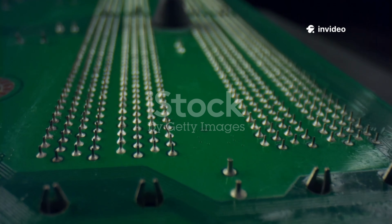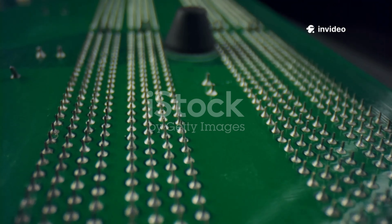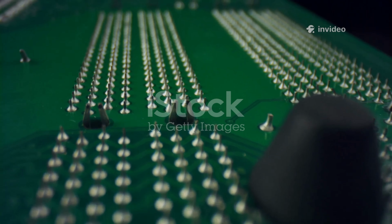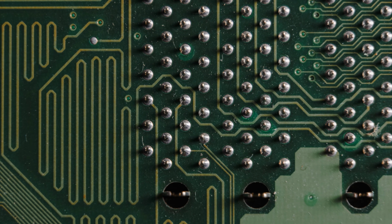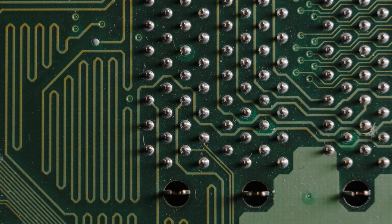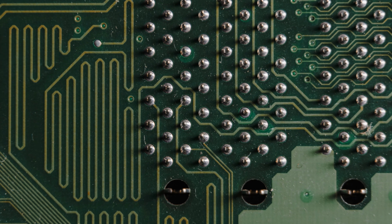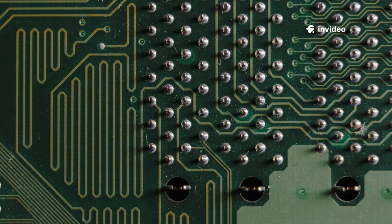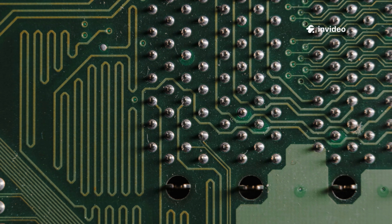When you add resistors in series, the total resistance of the circuit increases. Each resistor adds to the overall opposition to current flow. Conversely, when you add resistors in parallel, the total resistance of the circuit decreases. This is because you're providing more paths for the current to flow, effectively reducing the overall resistance.